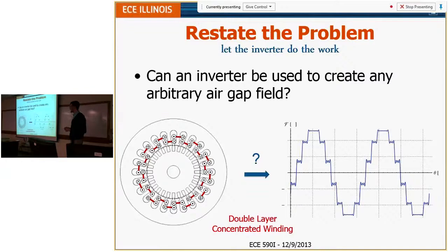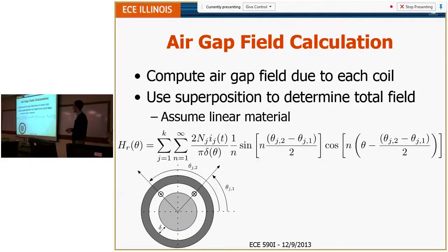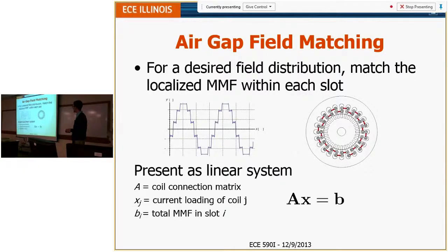All right, thanks. Carl? So just a couple of questions. One is that the equations you use to drive those curves are fairly simple. Yeah. Now, if I were to actually take that machine design, go to the next slide, and look at the oscilloscope, would I actually get that curve, without having to do a fancy finite element analysis? Yeah, you will. It's not going to be a sharp top like this. You'll have some other harmonics, but you'll see something similar. You'll definitely see a staircase function.